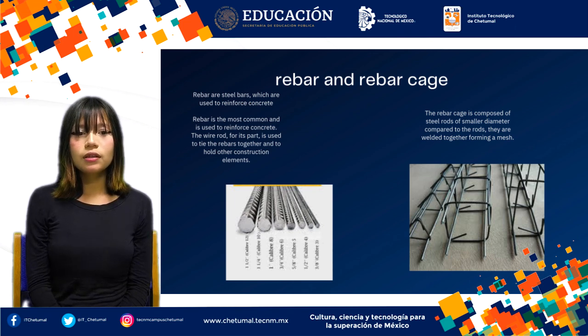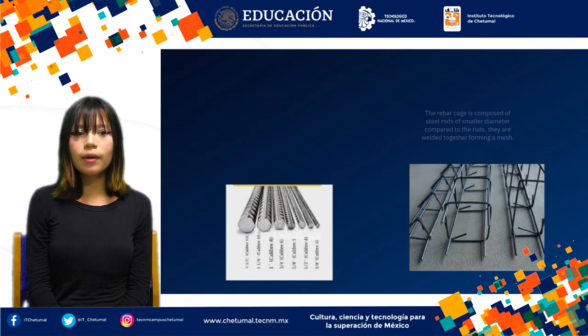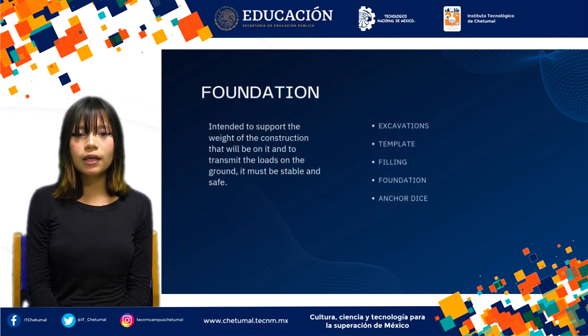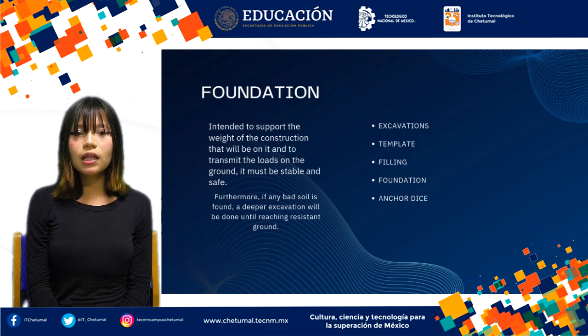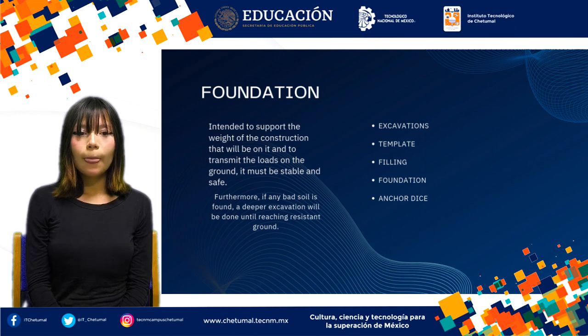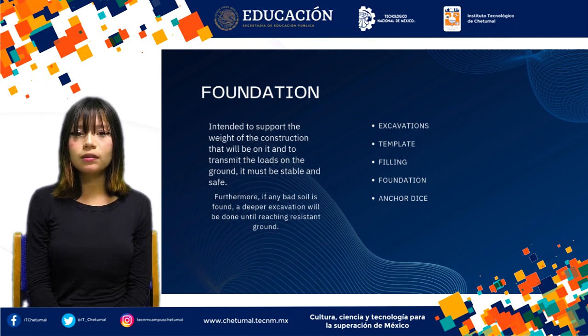Construction process. The stone is placed into a mixture of concrete or mortar in previously excavated trenches. This provides a strong and durable base, especially for small houses or structures that do not require deep foundations. Advantages. It is an economical option that can be quickly executed in rural areas. Additionally, the stone is highly resistant to compression, ensuring good load bearing capacity.